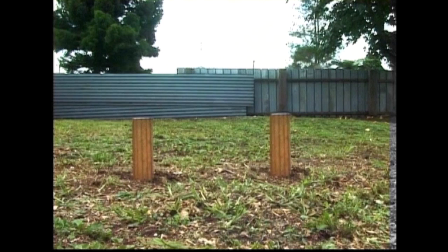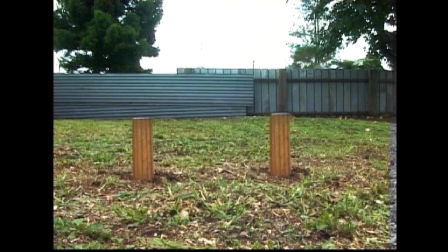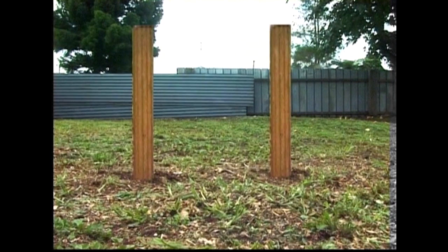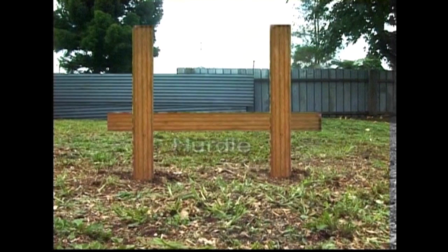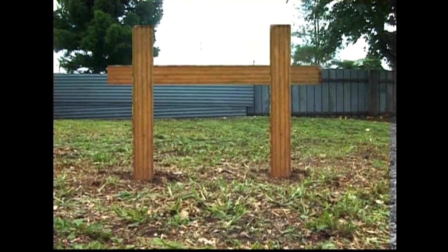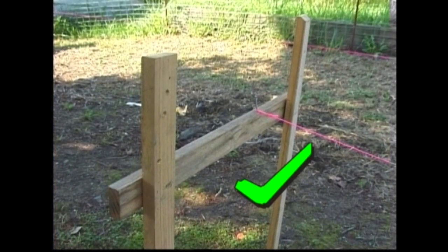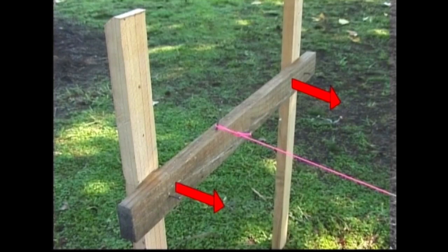Where the ledger is fixed to the tops of the pegs, a profile is called a saddle. Where the pegs are longer and the ledger is fastened to the sides of the pegs, the profile is called a hurdle. The longer legs allow the height of the ledger to be adjusted up or down during levelling procedures. It is good practice when using a hurdle to have the tension string line pull the ledger against the pegs rather than away from the pegs.